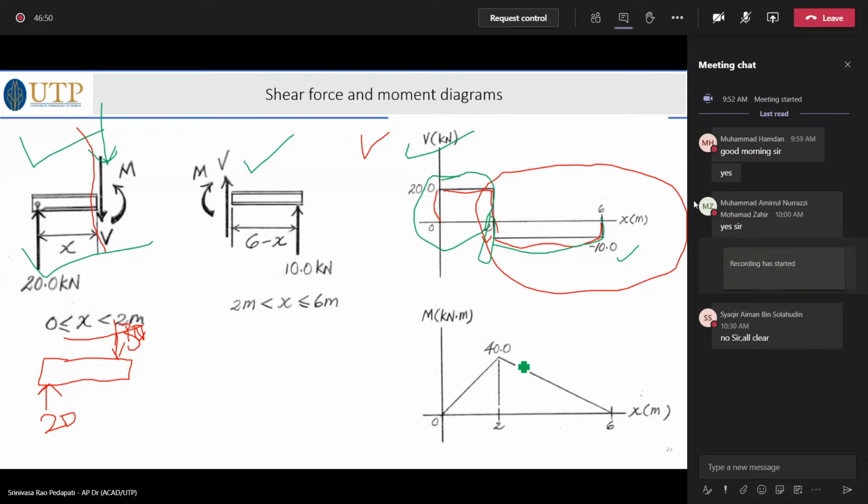So is it clear, the shear force diagram? What is the shear force? So if the shear force is clear, can anybody try to answer what is the bending moment diagram? The bending moment diagram is also similar. If you look at the diagram, it looks like a triangle. Why is it a triangle? What is the magnitude at the peak? At the peak there is some magnitude.